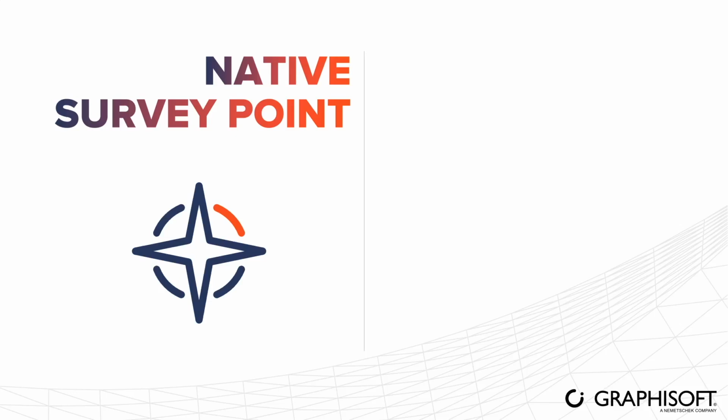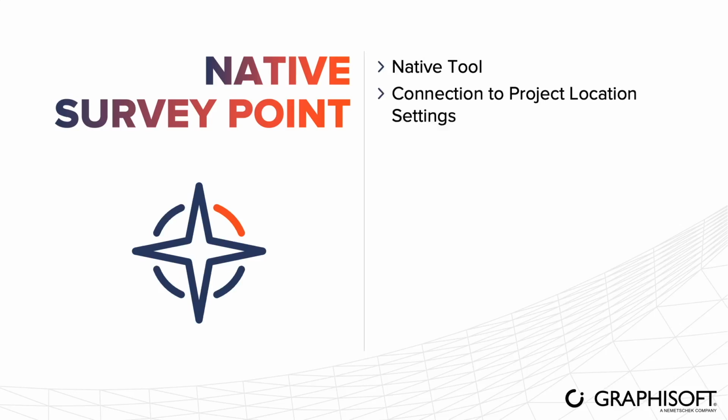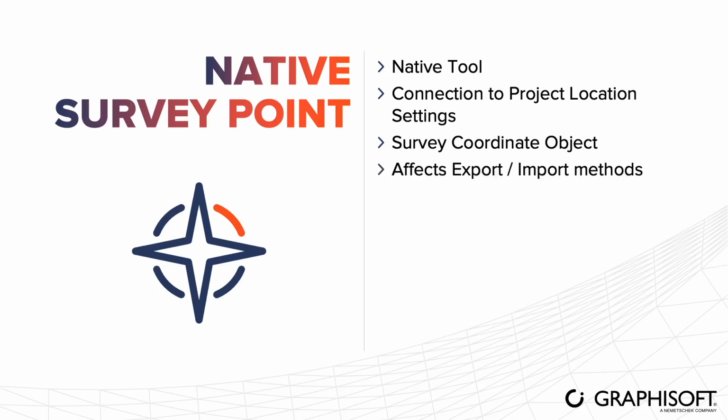Instead of having to rely on a GDL object, the new survey point becomes a native part of Archicad. It is now an integral part of the project, and its coordinates data is closely attached to the project's location settings. A newly added library part is capable of presenting coordinates in relation to the survey point for documentation purposes. The survey point now has a bigger impact on our exported and imported files.